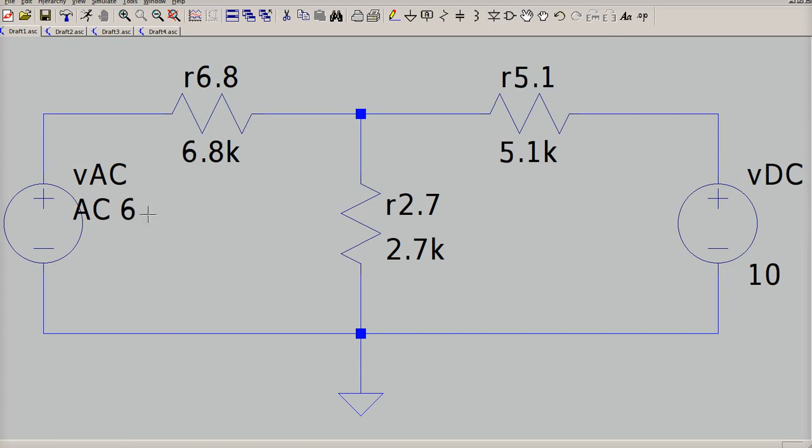So basically what I've got to do is I've got to take this circuit, and if my circuit has a voltage source, I can remove the voltage source and short it. If it was to have a current source, then I would just take the current source out and leave the open in the circuit. So that's how you do it, and that will also show up in Thevenin and Norton as far as doing the Thevenin and Norton analysis, which we get to eventually.